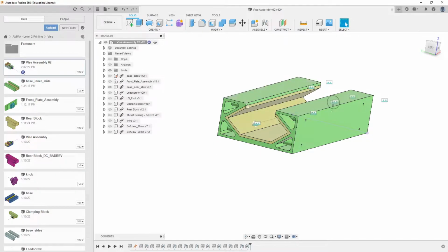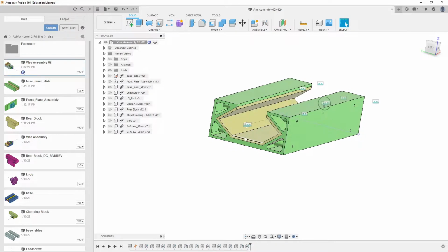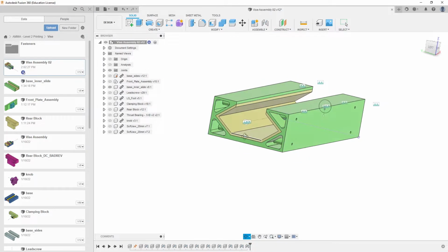So instead of trying to figure out how you're going to draw all this in one sketch, that is almost always the wrong way to do it. What we're going to do is make a centered rectangle that is the entirety of this whole thing, and we'll extrude that out. That'll be part one. And then after that, we'll cut out this inner feature. These little sections over here, we're going to worry about them later. We've got a different little trick to do with those, okay?